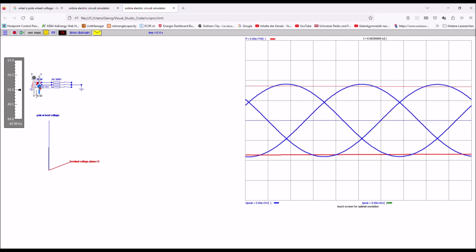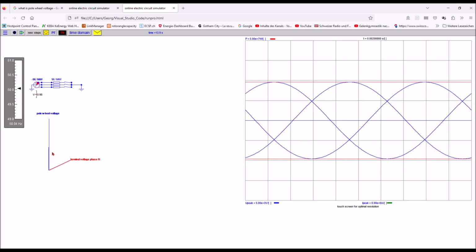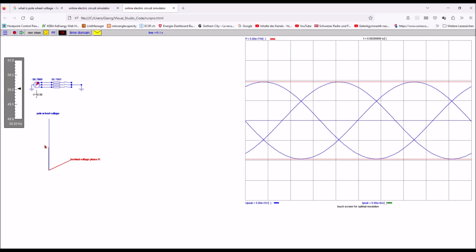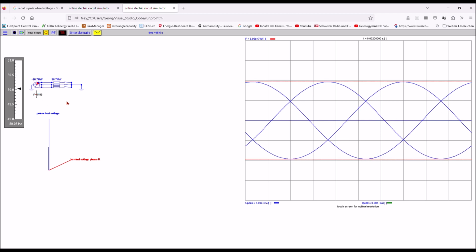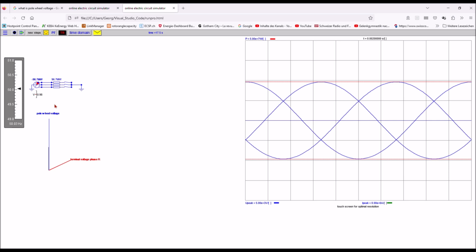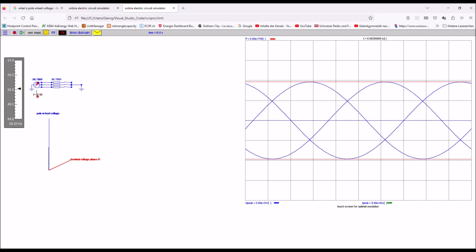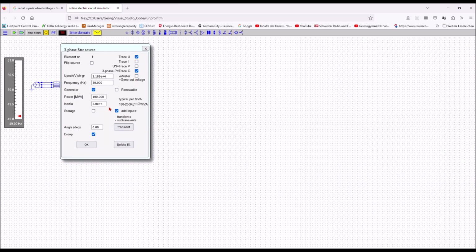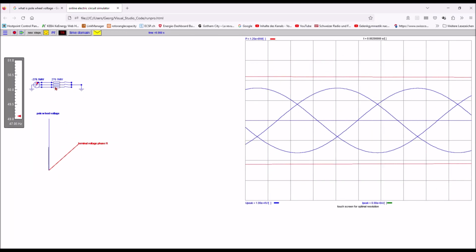Here is the slider adjusting this inner pole wheel voltage. The angle between the arrows is the generator rotor angle. It corresponds to the red circle segment on the source model. The indicator underneath the source is the generator terminal voltage in per unit of nominal. The red, blue and black arrows are not shown in the simulator, it is just for demonstration. By the way, I can also switch off this view meter if I want. You see it's gone now, it's not there anymore.